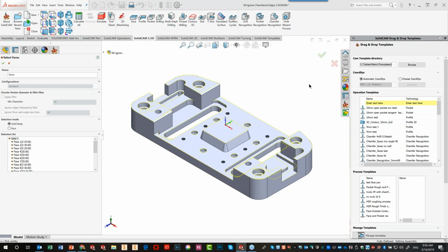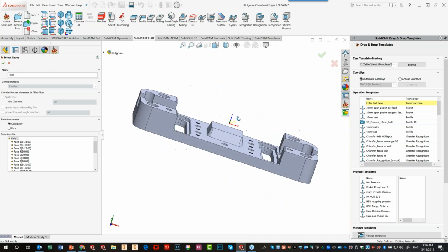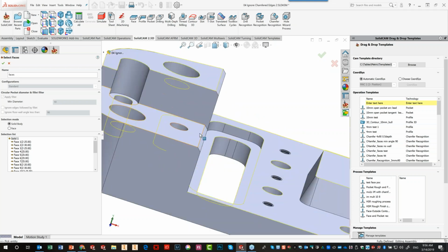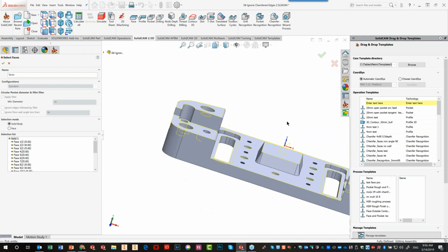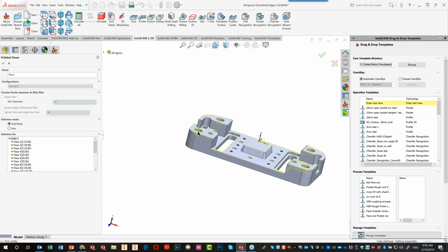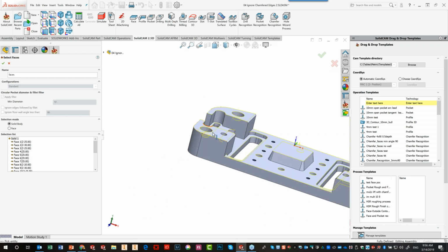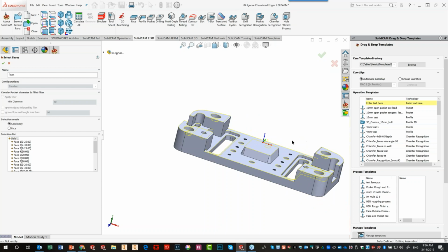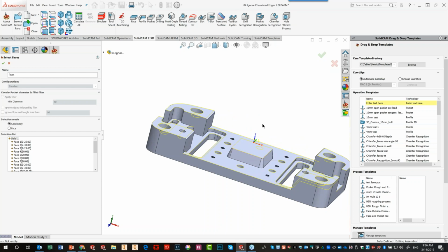And if I were to do a chamfer operation on this, I would actually end up ruining this area over here. By breaking the burrs on this, which is what I want to do over here, I would actually dig into this area over here, which I do not want to do. And the same thing may be true over here as well. So what can I do now? Let me unselect all.